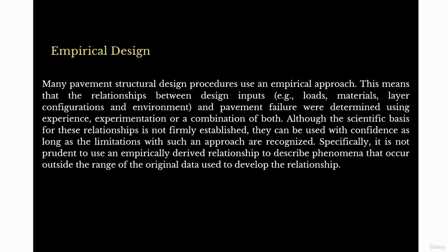So next we'll look at empirical design. Many pavement structure design procedures use an empirical approach. This means that the relationship between the design inputs, e.g. load, material layers, configuration and environment, and pavement failure were determined using experience, experimentation, or a combination of both. Although the scientific basis for these relationships is not firmly established, they can be used with confidence as long as the limitations with such an approach are recognized.